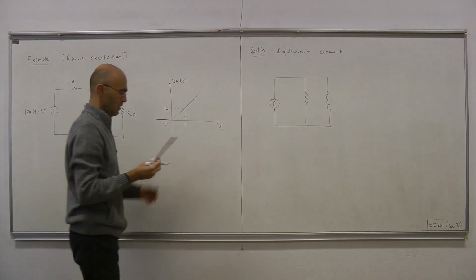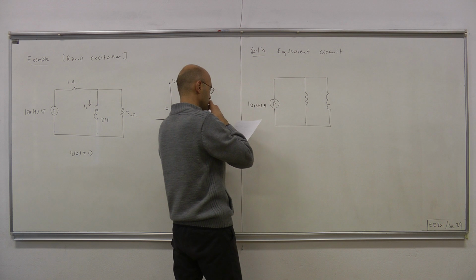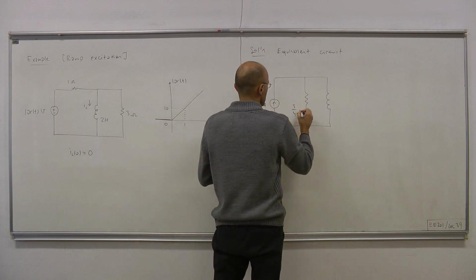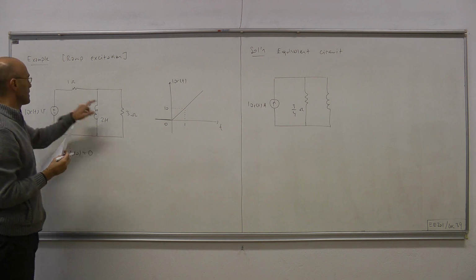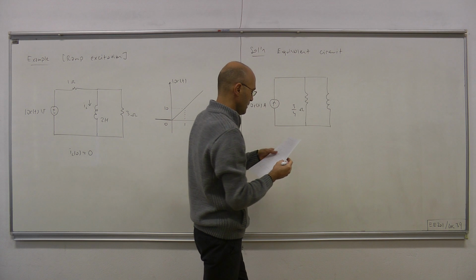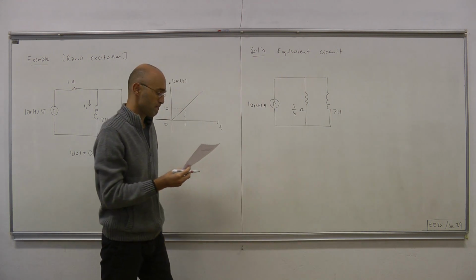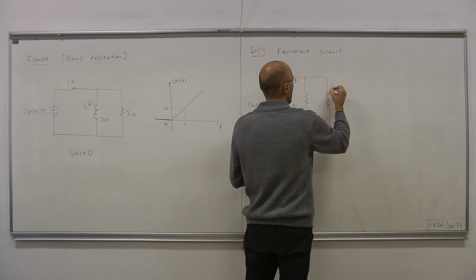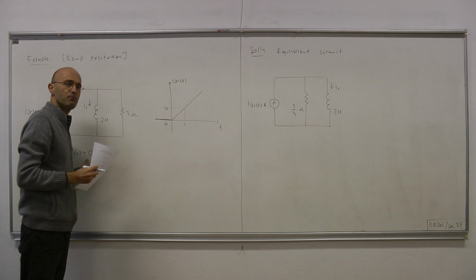Okay. Now here we have 10 r(t) amps. This is 3 over 4 ohms. This guy and that guy in parallel is the resistance seen by the inductor, and we have the inductor here, 2 Henry. Now we will try to figure out IL, and the initial condition is 0.